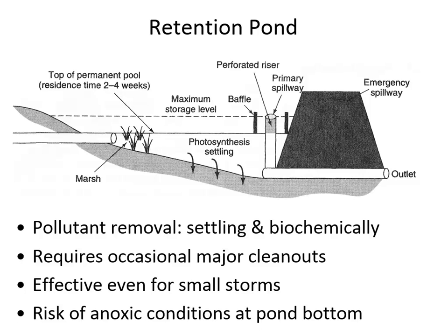One of the environmental risks is anoxic conditions, that means in the absence of oxygen. If the pond is really deep, then it might be that at the bottom of the pond there isn't enough oxygen diffusing from the surface layer, and there can be a sludge layer and bacteria that break down organic pollutants in the absence of oxygen, and it generates a really foul odor.